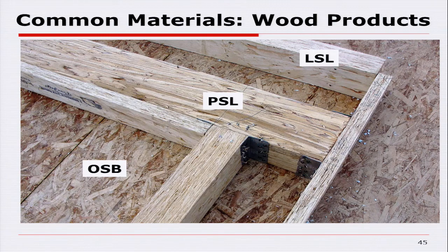This is just a job site. This is the house right behind my house, and they just built that one a couple years ago. And interesting, they've got a wall that's being framed out and it's laying on the deck, on the floor as it's being constructed. But interesting that I've got OSB, parallel strand lumber and laminated strand lumber all showing up on that job site. That whole house is being framed out of engineered lumber products. No solid sawn lumber in it. And that's high-end construction today.